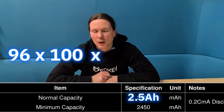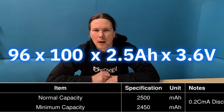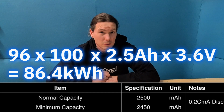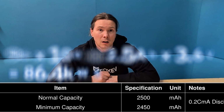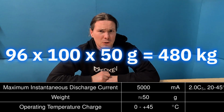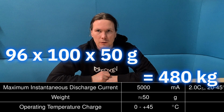Okay, but from the data sheet, we can do a little bonus calculation here. We've got 96 cells in series and 100 in parallel. Now, if we multiply that by the 2.5 amp and the 3.6 volts, we get the available power of the entire pack, which would be 86,400 watts or 86.4 kilowatts, which is quite a lot actually. It's quite a big pack for a car. Okay, let's do the weight as well while we're at it. 96 times 100 times 50 grams is 480 kilograms. That's also quite a lot for a car. So, not quite happy with either of those.